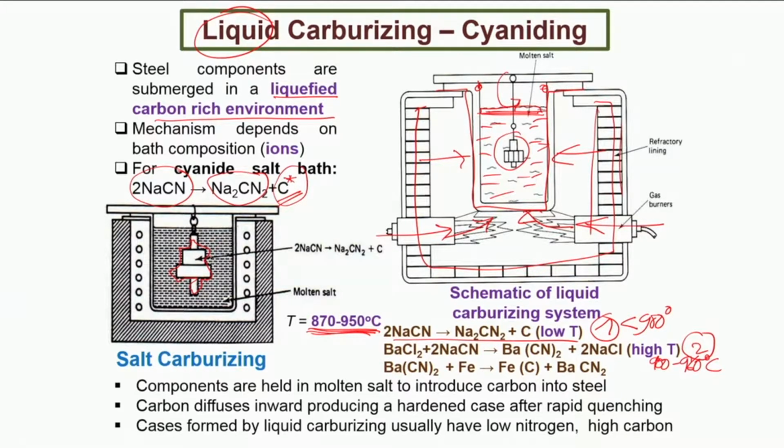And that we have discussed already in the previous lecture, that this diffusion depth, the so-called x of the diffusion, is a function of time, of course, at a given temperature T. So approximately we use an empirical relationship wherein we know that this is the depth which we expect for the diffusion of carbon, and this D in turn is a temperature dependent term which basically is derived from an Arrhenius relationship, which simply says that D is proportional to temperature.